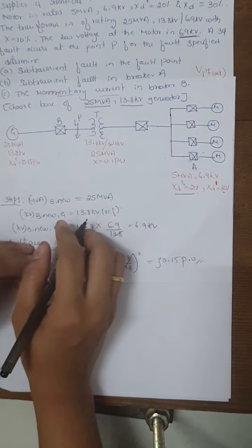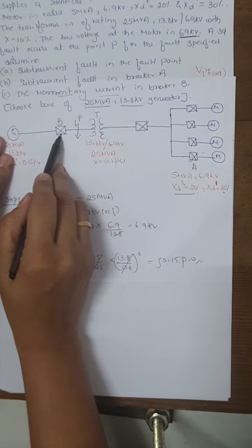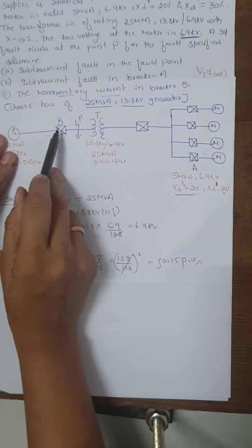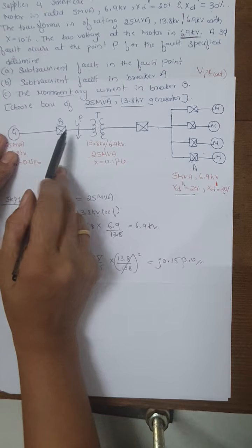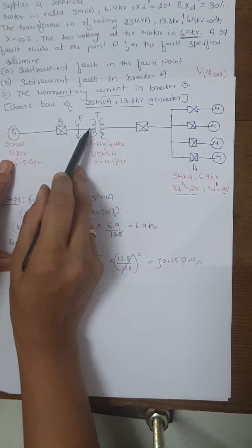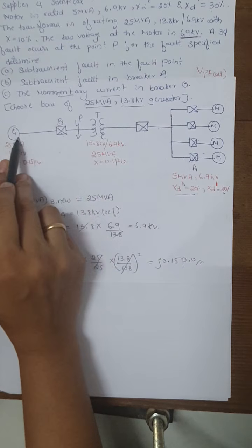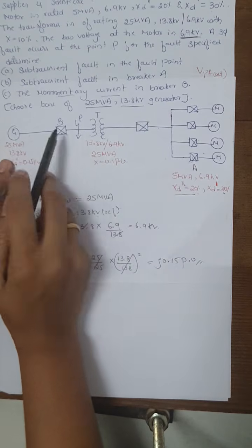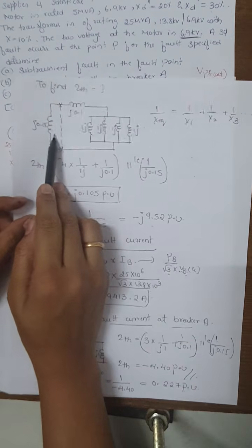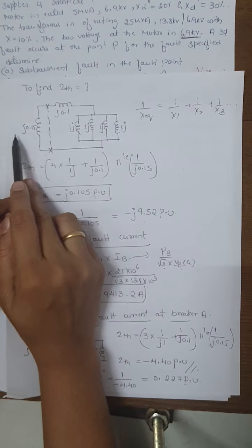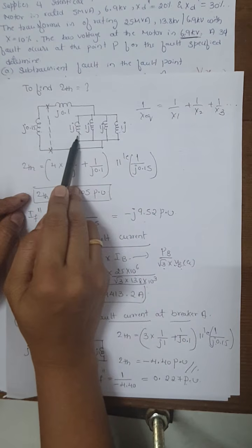For the third case, the circuit breaker needs to be energized because a momentary short circuit has occurred. Once the breaker B is energized, it is going to break its contact from the entire power system. Once this breaker B is disconnected, even the generator connected to it will be disconnected. So now the same reactance diagram we need to rewrite, but since the circuit breaker B is energized, this reactance is no longer connected to this power system.